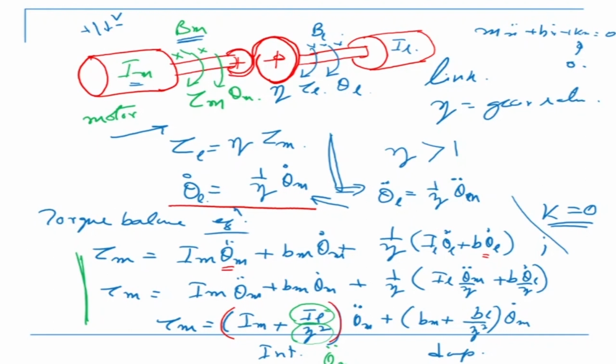So what is the moral of the story here? The moral of the story is that you must have a gearbox, and a high value of zeta for the gearbox. Please remember, if you're trying to control anything without a gearbox, especially a robot, you will not be able to control it. Because if there is no gearbox and there is any change in the inertia, your tuning will go completely off.